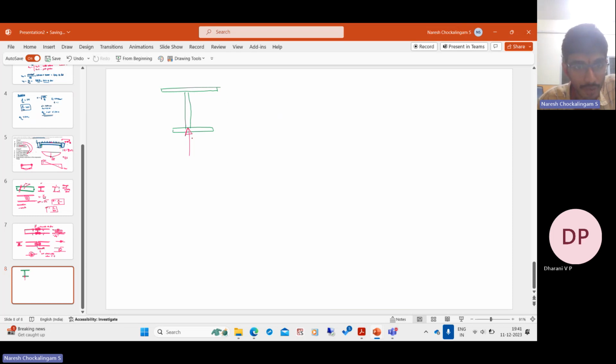At a single point, if you provide this kind of a very large force, what happens? The beam is intact, right? When we do our structural analysis, we assume that the beam is intact. Our moment of inertia is not affected, but this is also some material. Here you have a concentrated force, and here you have a sudden reduction of the cross section area. This is called the root of the cross section. At the root, the beam is particularly weak, so it can locally undergo material failure. This is called web crippling.